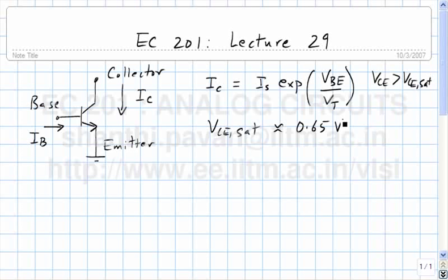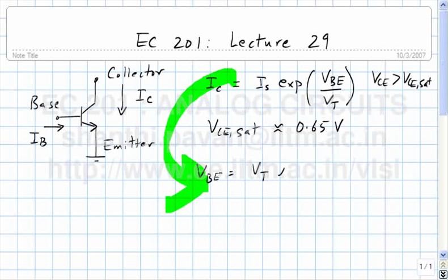So now the question is, what is a reasonable amount of collector current? A reasonable amount basically means something which is much larger than the reverse saturation current Is. In other words, you can see that VBE is given by VT ln of IC by Is. So as long as the argument of the logarithm is reasonably large, maybe 100 or 150 or 200, whatever, you know that the logarithm is a very weak function of the argument. So as long as this quantity is sufficiently large, if you look at the curve, you see that it's rising very slowly, and such amounts of current are not at all difficult to achieve and are used all the time in practice.